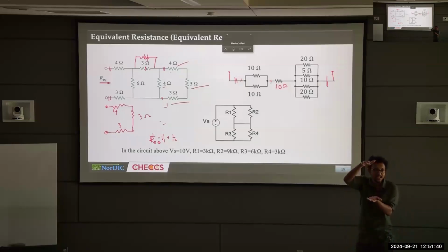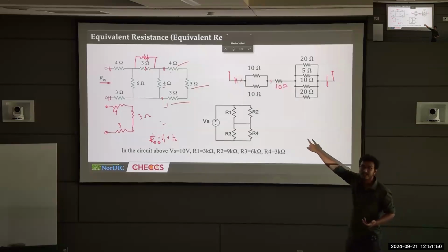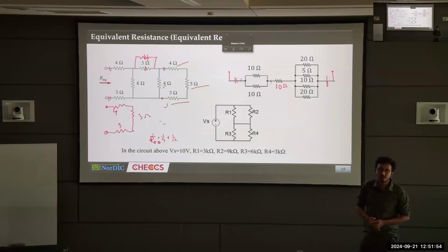If you have three 10 ohm resistances, you can just divide 10 by 3. You don't have to do the math all the time. Sometimes having the same value helps make it a shortcut. So if you have five 50 ohm resistors, you divide 50 by 5, which is 10. You can keep it in mind if you want.